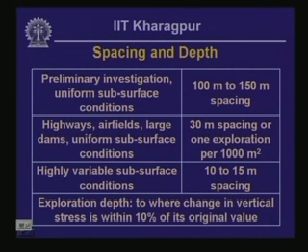If you have a very important structure and the project is at a detailed design stage, and the subsurface layers are uniform once again, the spacing is going to be much less, and the common practice is one borehole every 30 meters, or one exploration location covering approximately 1000 square meters.